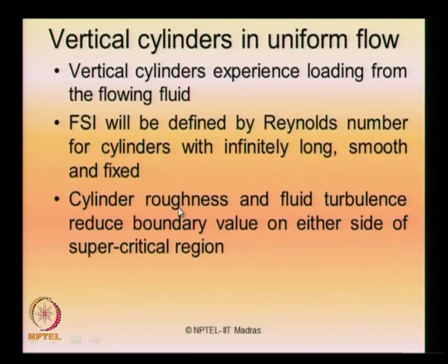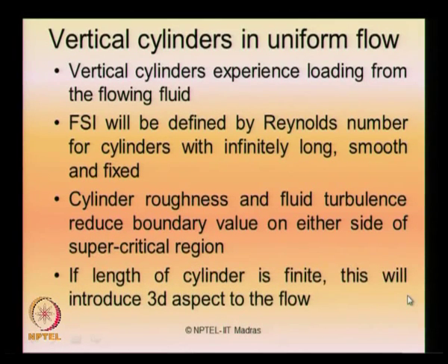The cylinder roughness and fluid turbulence reduces the boundary value on either side of the supercritical region, that is very important for us to understand. And of course, as I said, if the length of the cylinder is finite, then a 3D aspect also has to be studied in terms of the FSI. What we are talking about here is only the 2D aspect of FSI.